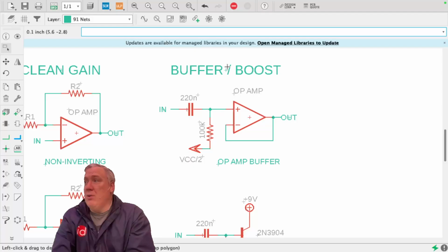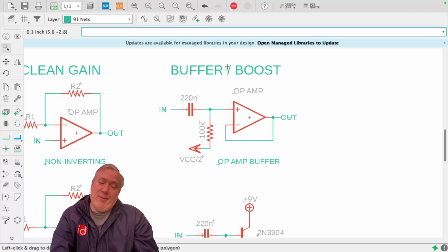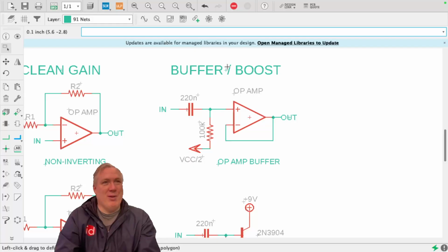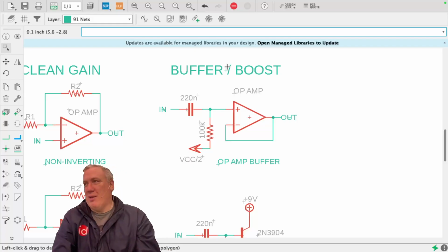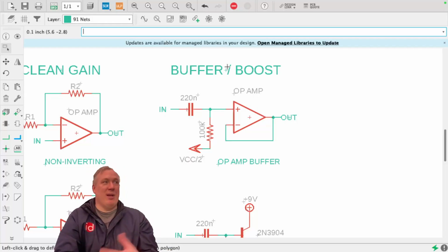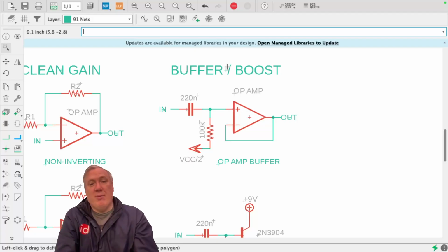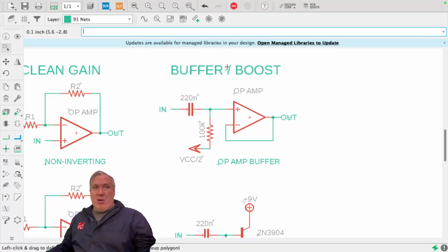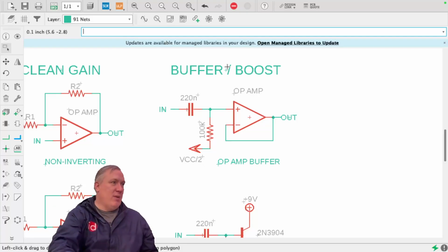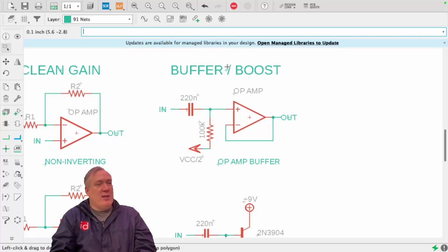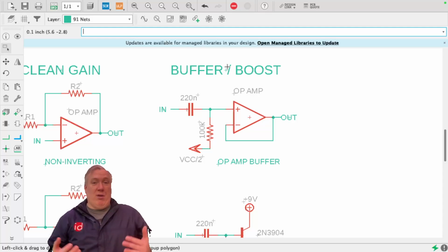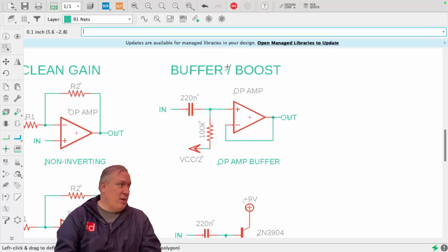If you use it when you don't need it, it actually is not a big deal, except for the fact that now you have a more complex circuit to build. So that's the only reason not to. It won't make it not work. It's just that some circuits don't play well when you plug a passive guitar directly into them. They don't work the way they should, and so they need a buffer in between. And some circuits are fine. They're fine on their own if you plug the guitar straight in.